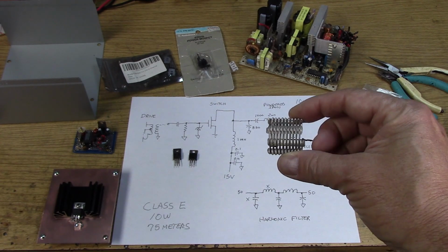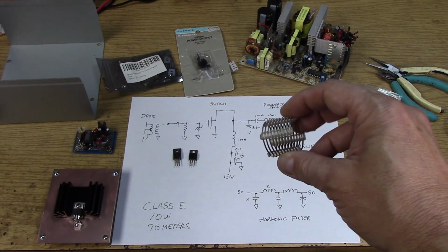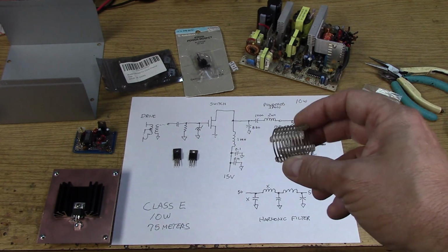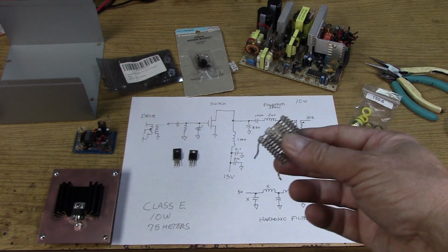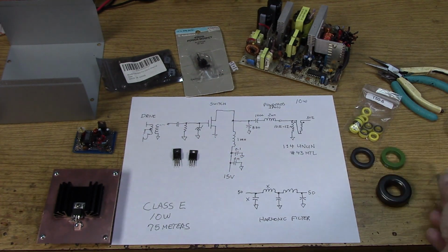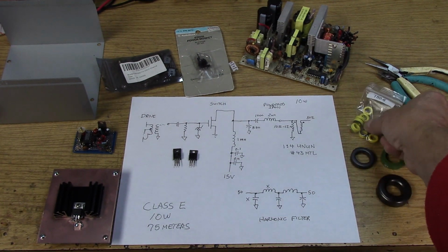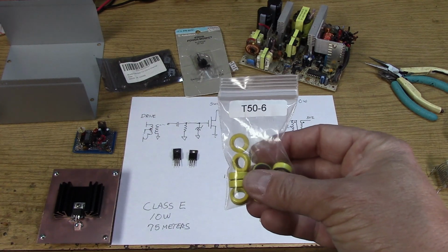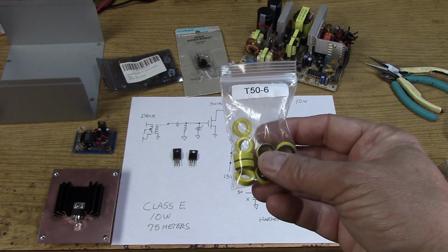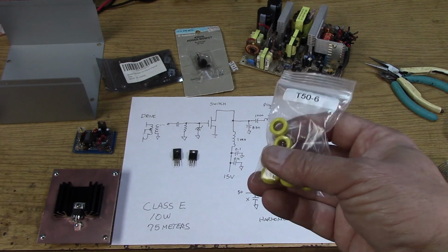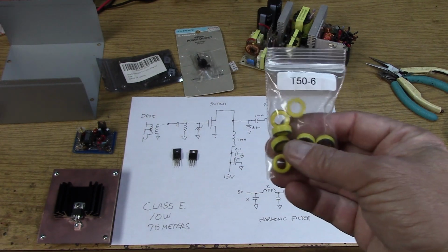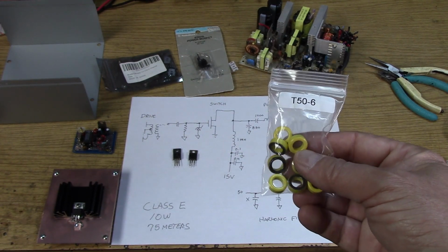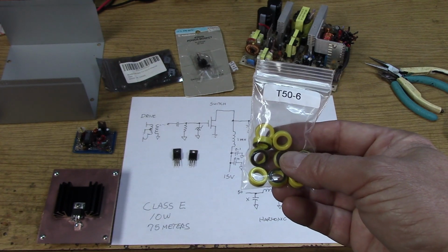You can make all the inductors with this kind of idea, just winding this on a 1-inch form or a 1/2-inch form. We can make the inductances we need. If you like to use toroids, I'm going to start out with the 1/2-inch size and work up to the 1-inch size and see if we get any efficiency differences. But the yellow cores, of course, are not preferred for this low of a frequency, but they are usable.